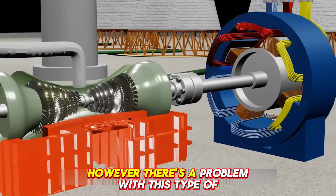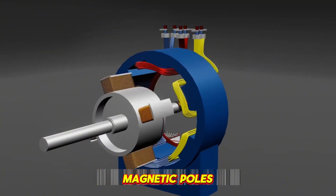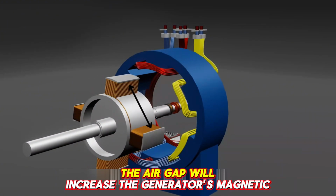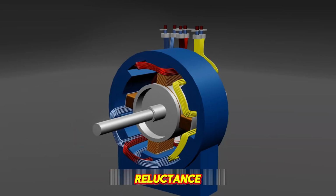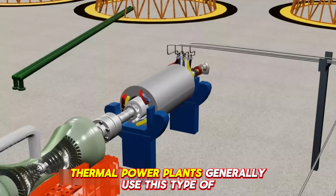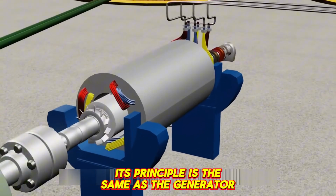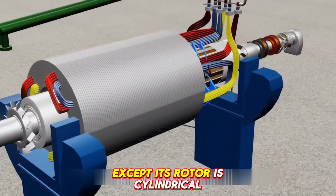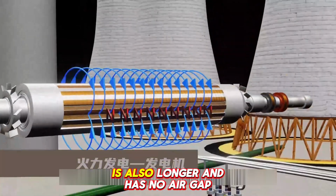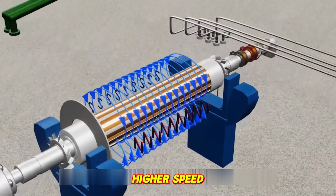However, there's a problem with this type of generator. There is a large gap between the two magnetic poles, known as an air gap. If the rotor spins at high speed, the air gap will increase the generator's magnetic reluctance, reducing its generation efficiency. Therefore, thermal power plants generally use this type of generator. Its principle is the same as the generator mentioned earlier, except its rotor is cylindrical. It doesn't have protruding magnetic poles, is also longer, and has no air gap, so the rotor can spin at a much higher speed.